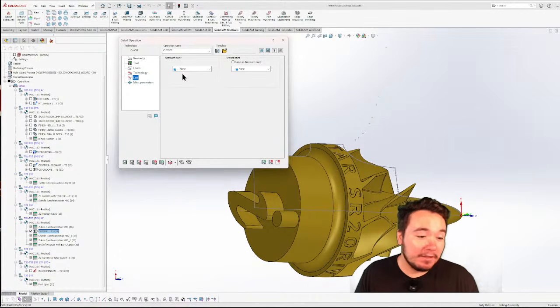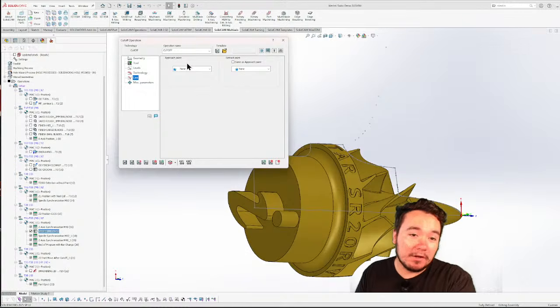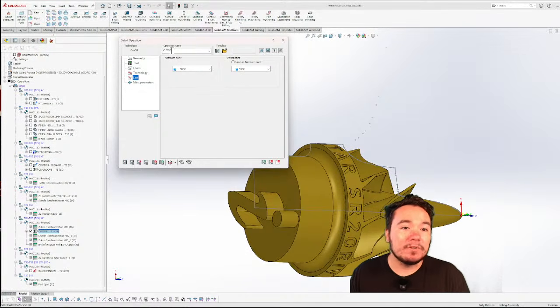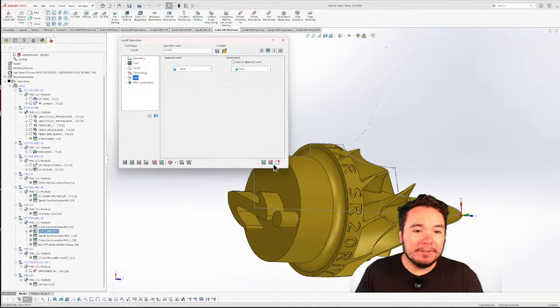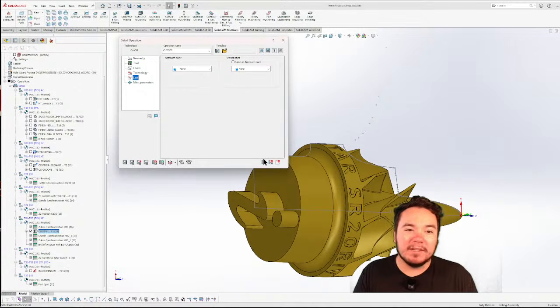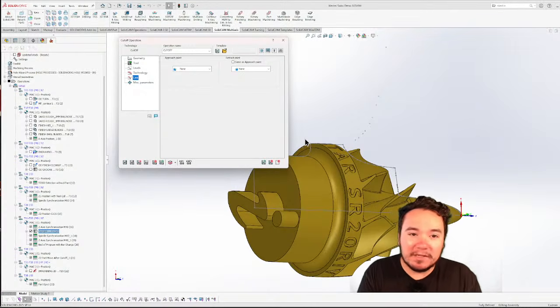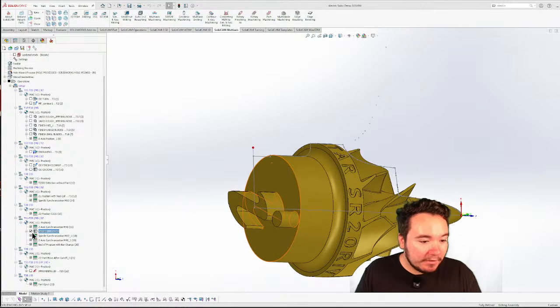For this one, you have to do no approach points or none when you're selecting that in the link page. Just a thing that you have to do because it's already set up, so you don't want the Z-axis trying to pull it anyway. So it's already ready to go. It's at the X position, it's at the Z position, it needs to cut out, and then boom, you just cut it. It might move just a little bit depending on if you measure everything correctly. But from there, you're good to go.